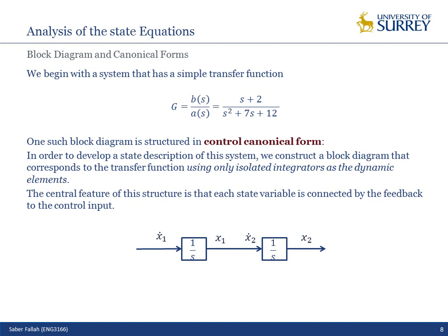For example, if you have rotary velocity, you need a tachometer to measure it, and if you have rotary displacement, you need an encoder or potentiometer. If we don't have a proper sensor to measure these states, we have some advanced mathematical approaches to reconstruct that signal, like observers, but it's beyond this course. Don't worry.